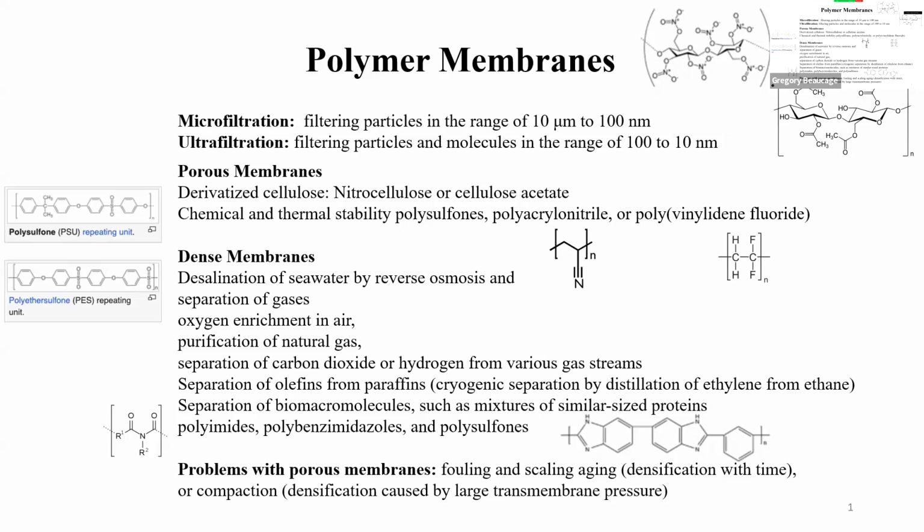So when you first go into the lab and say, I'm going to make a separation membrane, you take a sheet of plastic saran wrap and put it on a big thing like that. That's the worst thing you could do, because the force on that saran wrap is going to be huge, because it's the pressure times the area, and you have a big pressure and it just blows out and blasts through. So if you can make it into a tiny fiber and somehow wrap it up so everything is really small, but you have a large scale flux through it.